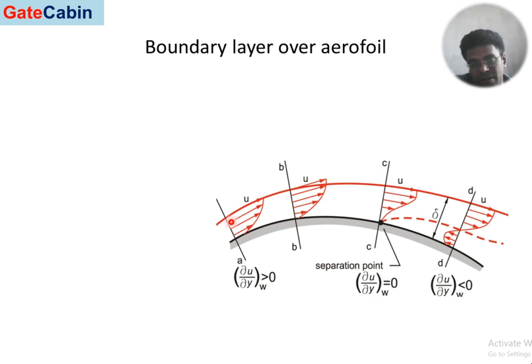As the flow moves over the surface of an aerofoil, at a certain point it is quite possible that the velocity at the front position will be lesser than the velocity at the rear position, the backward point, right? So in this region flow reversal takes place. This is the point where the pressure is less than the atmospheric pressure. So the atmospheric air tries to enter the region to interfere with the flow which is taking place on the aerofoil surface.